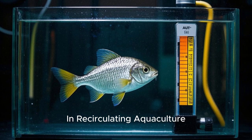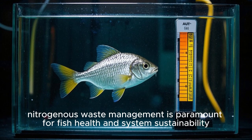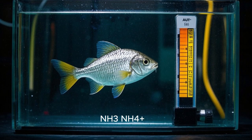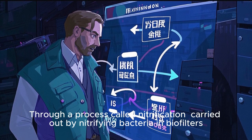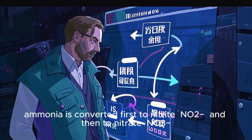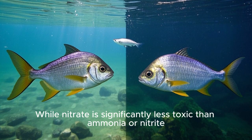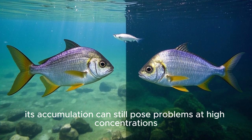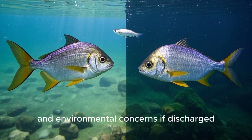In recirculating aquaculture systems, RAS, nitrogenous waste management is paramount for fish health and system sustainability. The primary waste product from fish is ammonia, NH3/NH4+, which is highly toxic. Through a process called nitrification, carried out by nitrifying bacteria in biofilters, ammonia is converted first to nitrite, NO2, and then to nitrate, NO3. While nitrate is significantly less toxic than ammonia or nitrite, its accumulation can still pose problems at high concentrations, leading to chronic stress, reduced growth, and environmental concerns if discharged.